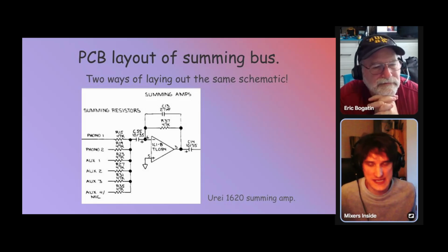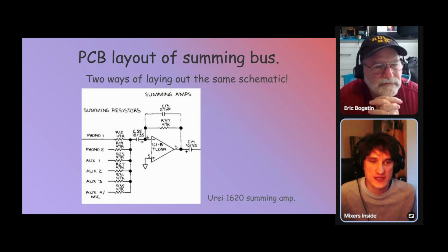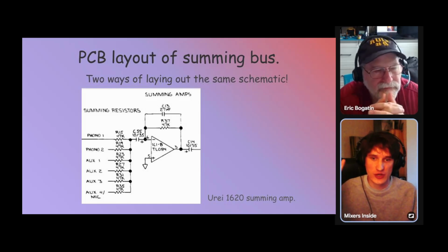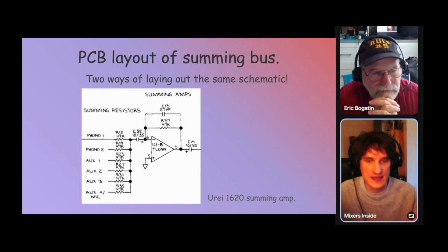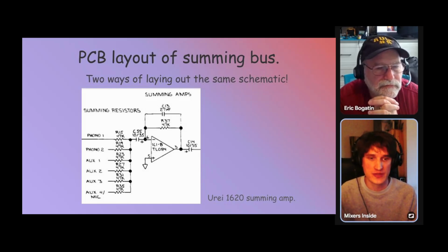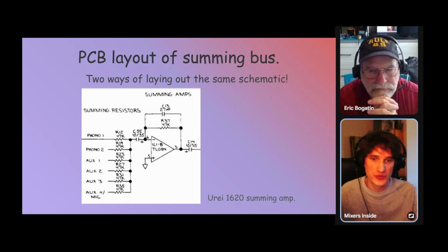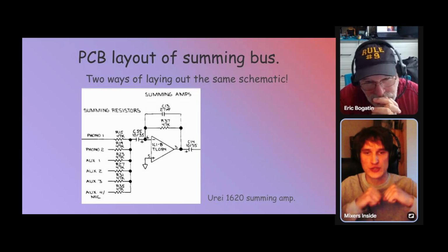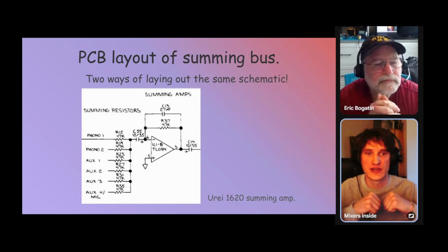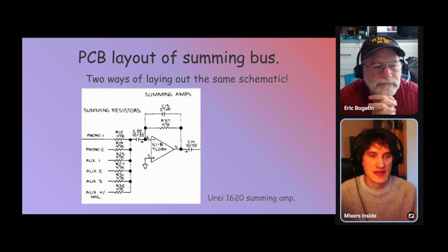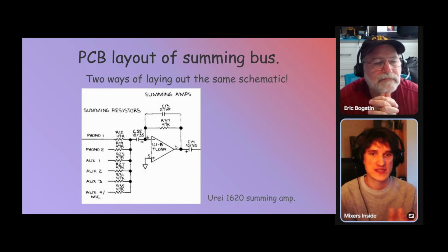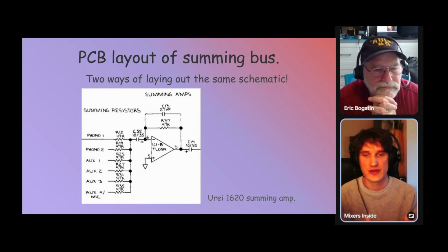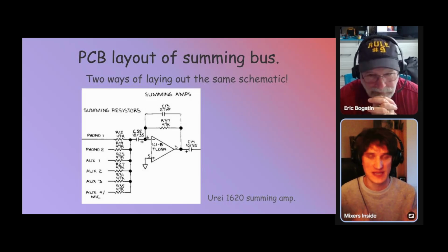The summing bus that is most popular in mixers is just an inverting configuration with, let's call it, virtual ground. Yeah, the inverting input of the op-amp, due to the non-inverting input that is connected to the ground, is still struggling to keep the potential at the ground level, right? And this is a very interesting example of what we were talking about at the beginning of our conversation,